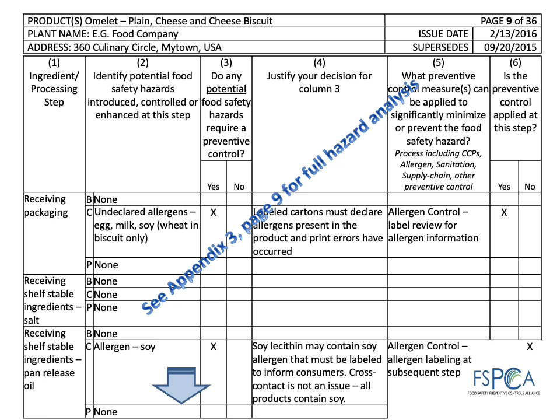Recording the rationale for the decisions made regarding hazards and preventive controls is useful to explain to others how the decision was reached. This is done in Column 4. For hazards requiring a preventive control, a yes in Column 3, the preventive control that needs to be implemented is identified in Column 5. Column 6 identifies if the preventive control occurs at this step. It may occur later in the process, and that step would be marked as a preventive control.